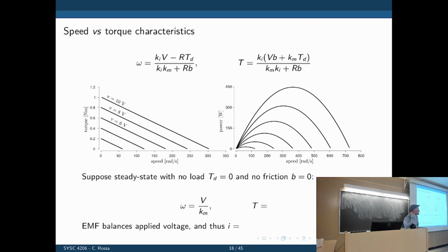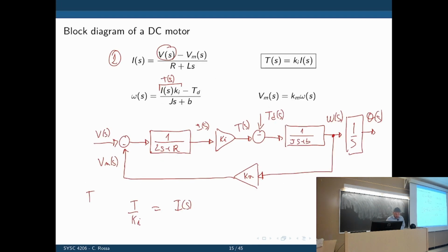Why is that the case? Because more speed, there's more back EMF. Aha. Because the more speed we have, the greater the back EMF over here, the smaller the net voltage that creates a current. Right? Very good.